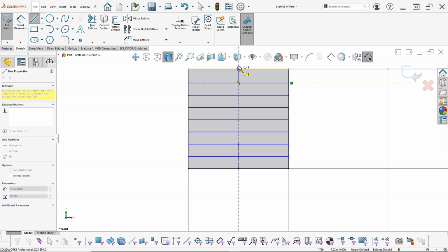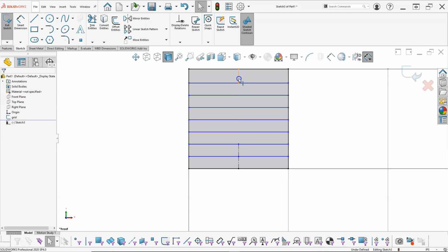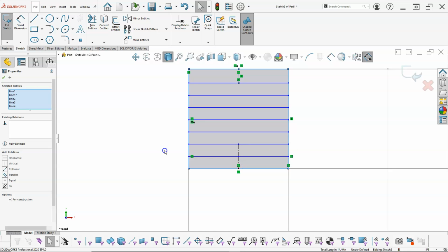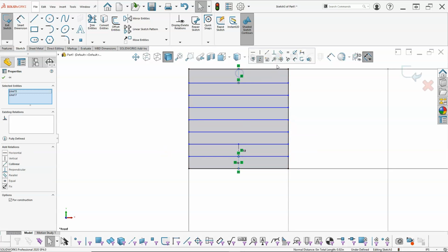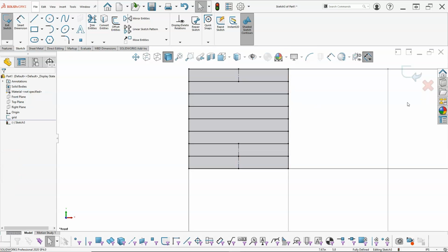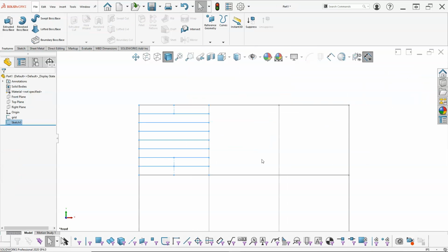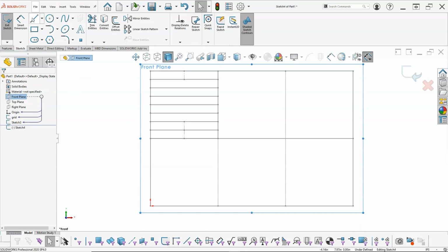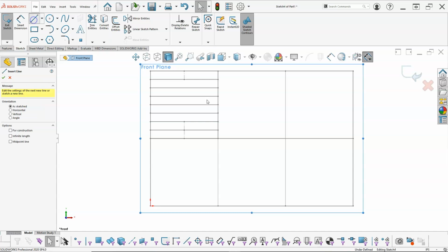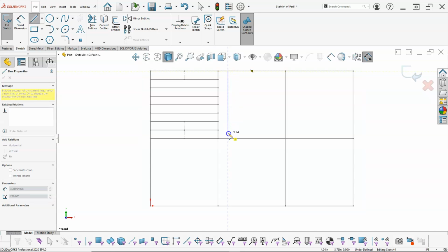Alright, so since it can still move, I'll go to the opposite. Select and Control Select and set to equal. Alright, so that gets me fully defined. Because of the linear sketch pattern, the sketch pattern is going to control the rest. I might not have needed this one if I'd done that over there, but at least the additional two gets me to fully defined. Other than setting up and exploring these patterns, if I needed to build geometry, the center line's not going to participate anyway.